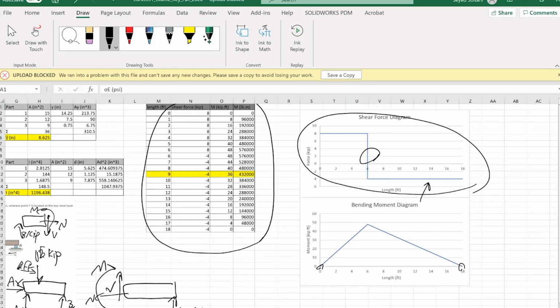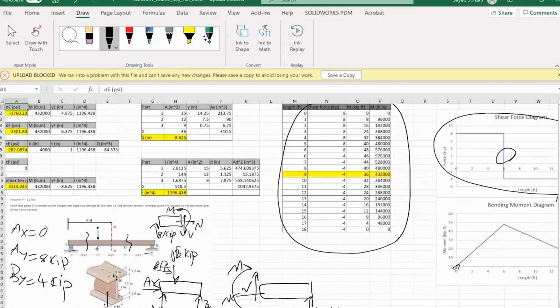You can use different methods, the easiest of which would be cutting a section exactly where this load P is being applied. So let's just do that now. I have 8 KIP, which is being used here. And then I have this distance, which is 6 FT per diagram, 6 feet. And then I have this normal force, I have this shear force, and then I have the bending moment. And there's nothing else. And again, what is it that I'm trying to obtain here?